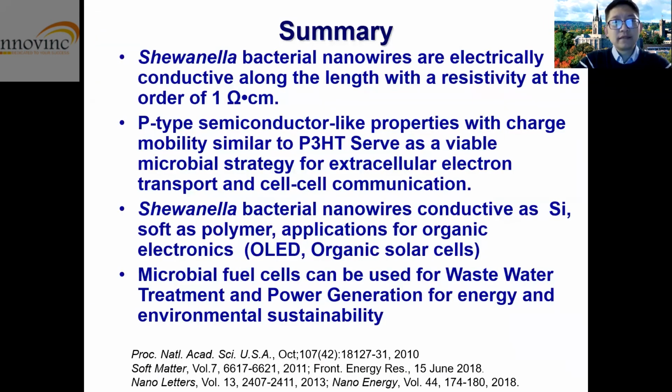So to summarize, Shewanella bacterial nanowires are electrically conductive along the length, with a resistivity on the order of 1 ohm centimeter. And this bacterial nanowire is a p-type semiconductor, which also has very similar charge mobility to P3HT, which indicates maybe this bacterial nanowire can be a replacement for P3HT.